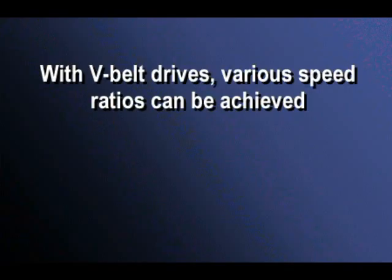An advantage of driving a pump with belts is that various speed ratios can be achieved between the motor and the pump. To change the speed ratio between the pump and the motor, it is only necessary to change a pulley.